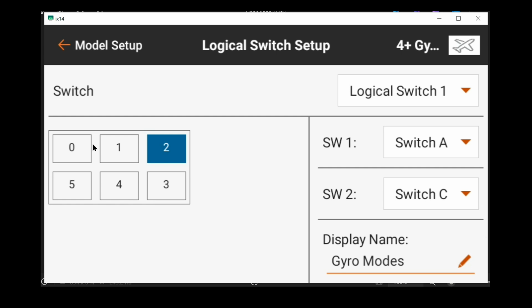In other words, if all of these are 0, we could set that for AS3X off and safe off. And then we flip the switch the other way, FM4. Then we could have AS3X and we could have FM5, envelope mode. And in 5, we could have safe mode, FM6. So you can have anywhere from 4 to 6 different flight modes, depending on how you pick these numbers.